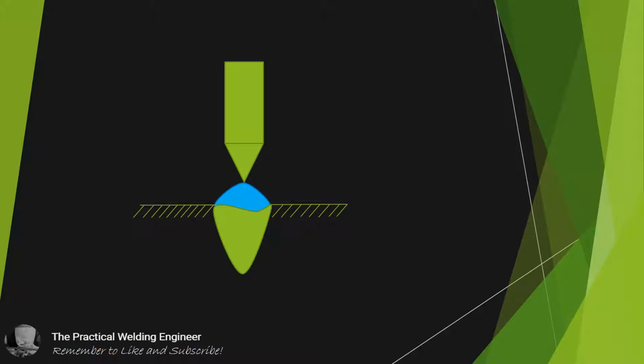So arc energy or heat input. Which one's which? Well, here we have our arc flashing away to itself. Which area is arc energy and which area is heat input? They're different between the specifications we use. Arc energy is the measurement of energy produced within the little blue flashing light that is our welding arc. And heat input is the value that is transmitted from the welding arc into our base material.